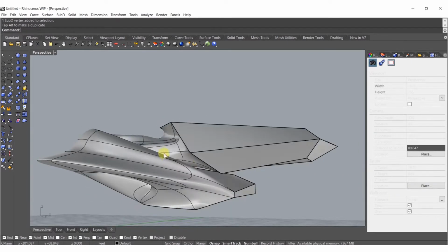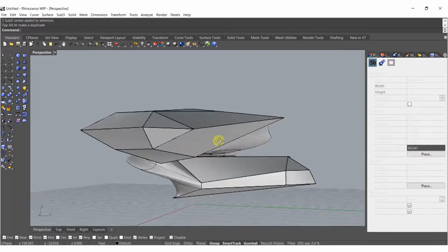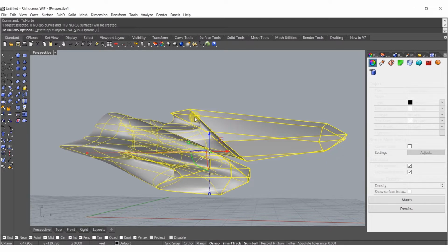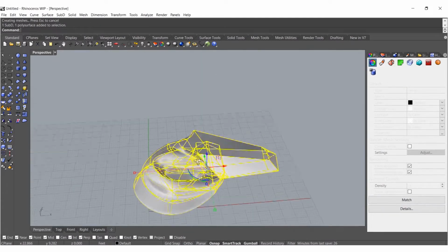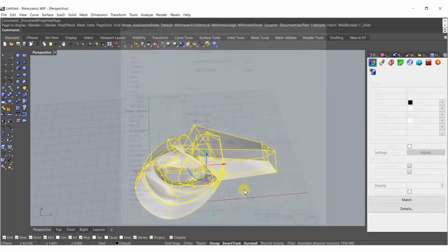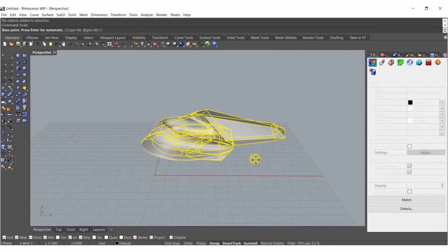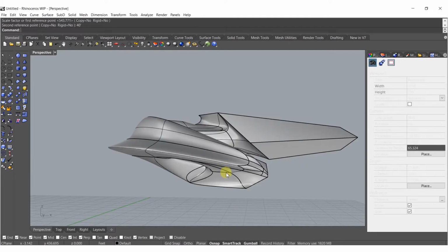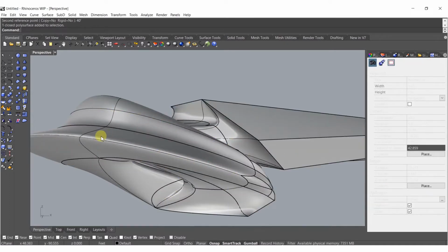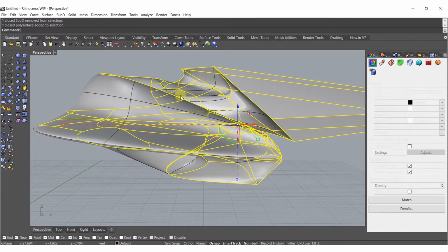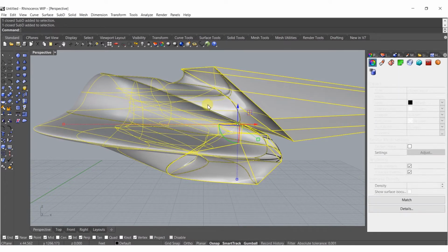All right, so I think that's looking pretty cool. So from here, what I want to do is we'll just convert this to a polysurface, and I'm going to check the scale on it for once, and we're going to type in units. I want it to be in feet. We're in feet, and let's just scale the whole thing, because with the Grasshopper stuff, we don't want it to get super crazy. So I just made that 40 feet for now. Okay, looks pretty good. And let's select our SubD there. We're just going to hide it for now.